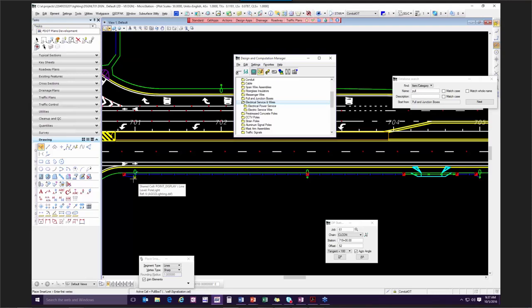These are not exact numbers. If you read the basis of estimates, this is a kind of compromise. You need extra line in order to make these connections. Giving you 8 feet at the pole box and 8 feet at the pole gives you that extra length in order to connect these lines in.